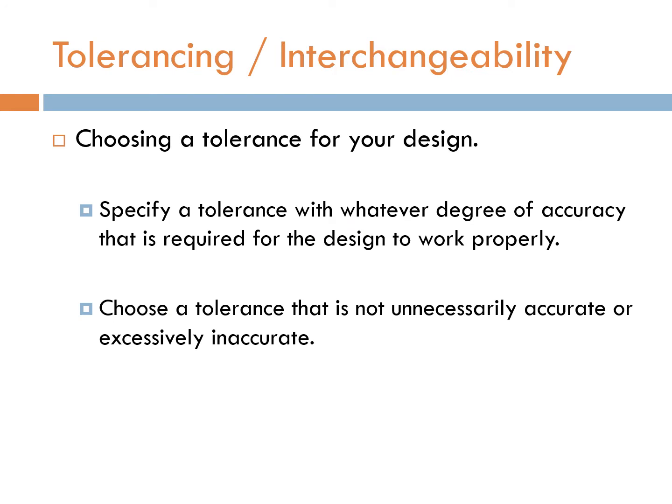When you design something, you have to think about the purpose of your project or your product. Do you need a very precise tolerance, a very small tolerance, to get a more precise dimension, or can you allow this variation to be larger? If you allow the variation to be larger and it is not critical, then you might be able to save a lot of money. That is the reason you should pay attention when you design. You have to pay attention to what kind of tolerance you are going to use.